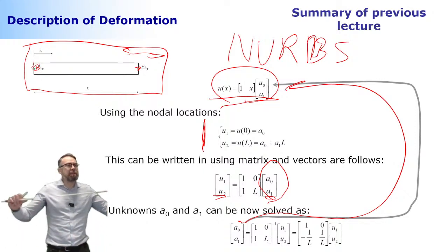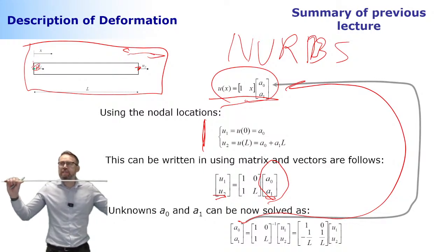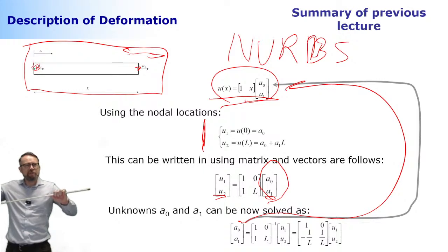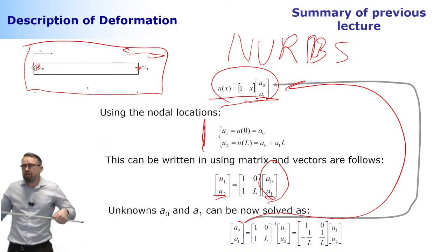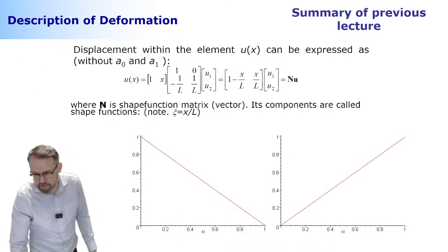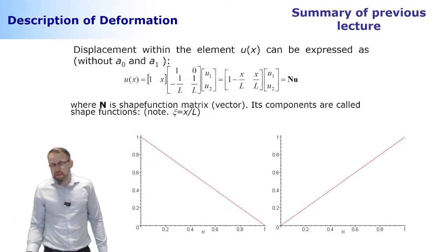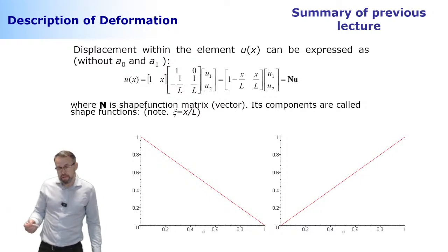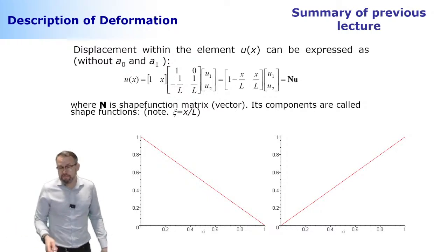Shape functions tell me what kind of deformation one element can capture. That's what it is. But this is a piece of the solution. And when you keep on adding these pieces of the solution, you get the entire solution of the structure under investigation. That's how it goes. So it's a piece-by-piece solution. Like here, it is a linear polynomial expansion, and the shape functions are linear.